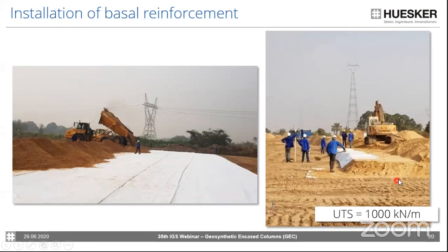When the design requires it, a wraparound is also installed, that means that at both sides of your embankment slope toe, the geotextile is lifted and then wrapped around and back anchored. This gives you a nice anchorage and also helps to reduce the lateral deformation in your embankment.